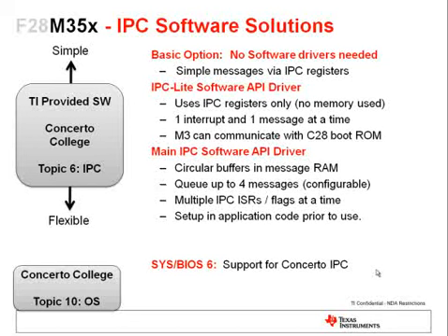The basic option is a very simple measure that does not require any drivers. This option only requires the IPC registers to implement very simple flagging of messages passed between the processors. The next step up are the IPC drivers. Some applications need more structured, driver-based functions for reading or writing data, setting and clearing bits, and function calls. TI actually provides 2 sets of drivers, IPC Lite and the main IPC API driver.